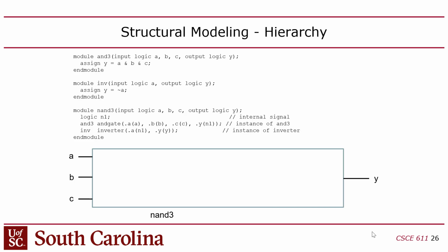So what this is doing is creating a top-level design called NAND3 that has top-level inputs A, B, and C and top-level output Y. That's the pinout, right? Now on the FPGA, if this were the top-level design, the root of the design tree, all of these inputs and outputs would have to match the exact names of pins on the FPGA, to actually connect these things outside the chip, right? Whereas everything underneath there could be arbitrary, right?